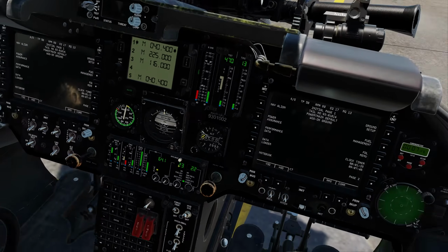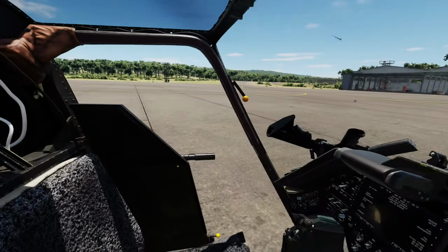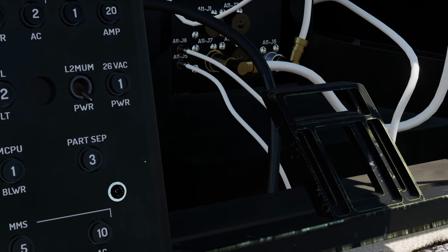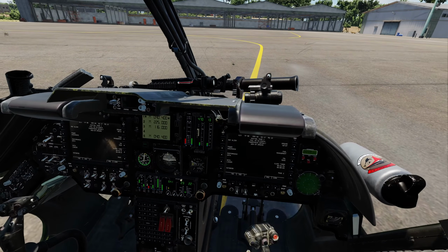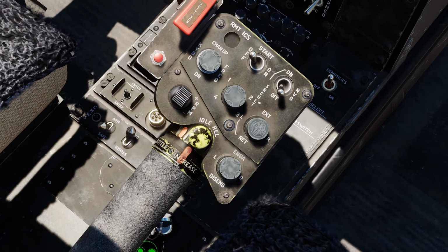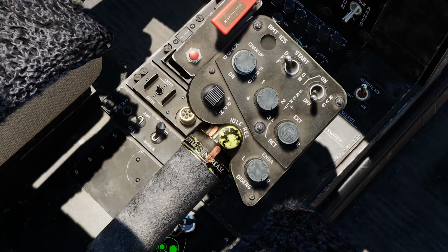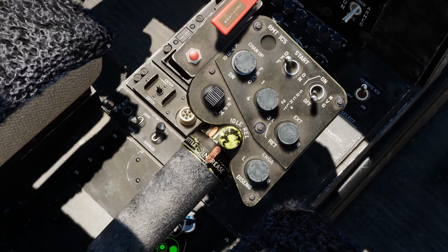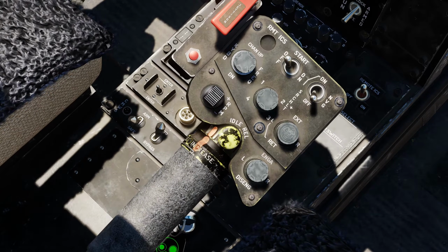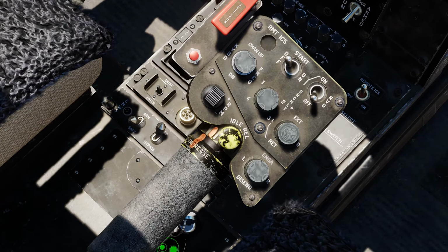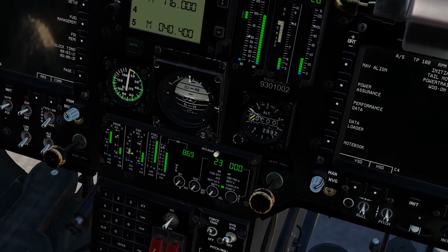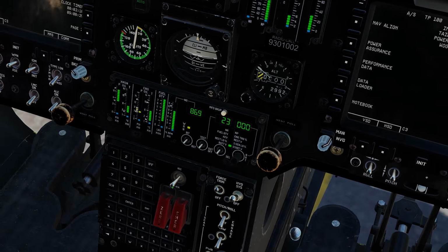Acknowledge them. Okay, now we've done that, we need to put the particle separator in, which is this fuse here at the back. See that particle separator? Click that one in. What we need to do now is we can open up the throttle gently to the maximum position, fully open. And we'll do that slowly here. Okay. Here we go. Up, up, up. Now it's important we do it slowly, obviously. I don't want to overstress the engine as we do that. Okay, and certainly we heard a warning there, but there's no other warning signs up there. We'll acknowledge it anyway, just in case.